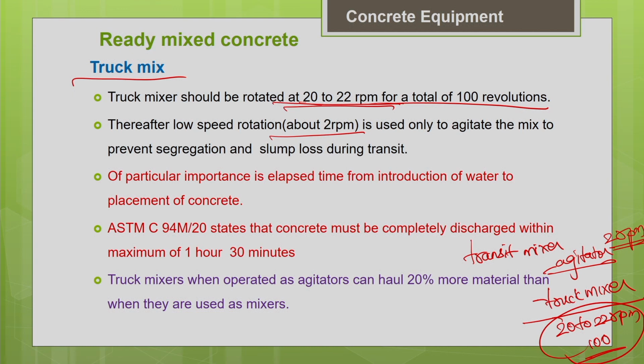So, generally when you use a transit mixer as an agitator, I can use more capacity of the truck than when I use it for preparing the concrete. Okay. So, the important thing to be noted is the elapsed time from the introduction of the water to the concrete to the placement of concrete. That is very important with respect to concrete. The time is very critical, because as I told you, once you add the water, the cement starts hydrating, it starts stiffening, your setting will start. Okay. So, that is why there will be loss in workability during the transit.